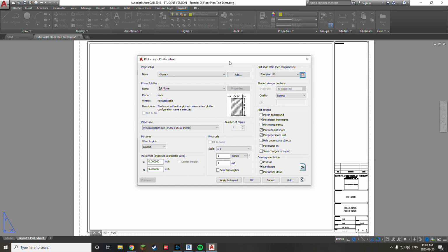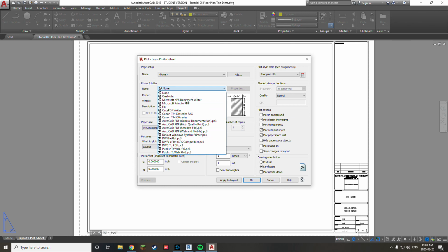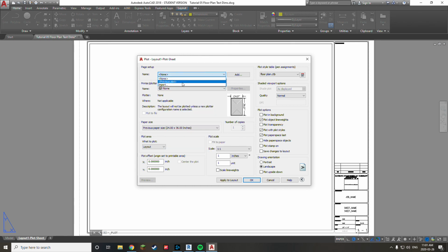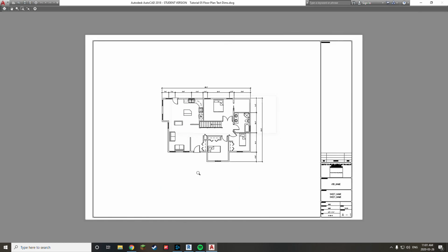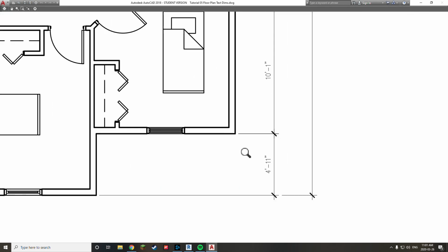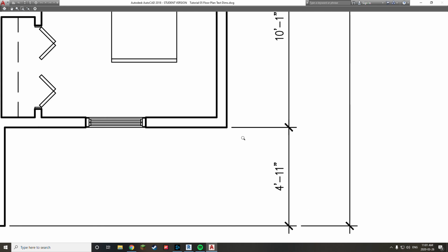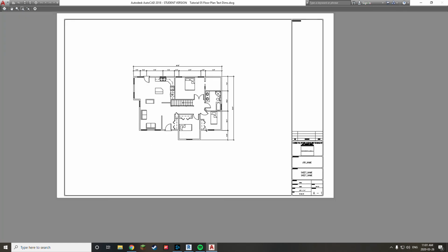Save and close. And notice that it didn't keep the settings from last time, like I chose a PDF creator, all that stuff. If I use previous plot, it should find the settings from your previous plot if you have by chance printed. Anyway, I'll click apply so it saves these settings to this drawing. I've got a PDF creator, drawing to PDF. This still matters. Sheet size is set, scale is set. One last preview. Looks good. I zoom in, and you can definitely tell there's a difference now between the line weight of the walls and that of the dimensions, right? So it still applies line weight even though it's a PDF.